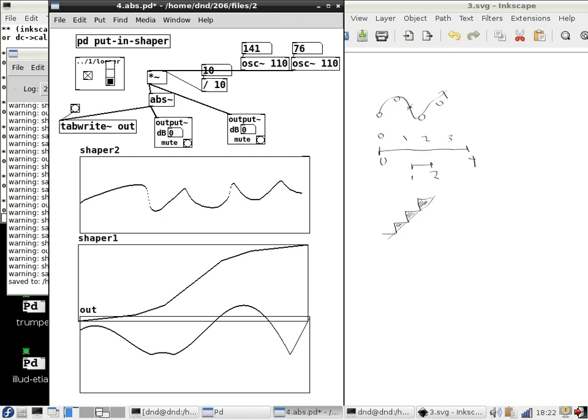That has about 1 in 10,000 amplitude, and that's audible. That's minus 80 dB compared to the original tone, and so that's already an estimable amount of foldover. That can be made to sound bad. And again, the higher the frequency, the higher the pitch of the thing that you put in, the worse that situation gets. So that's the thing that one wants to be able to control somehow.